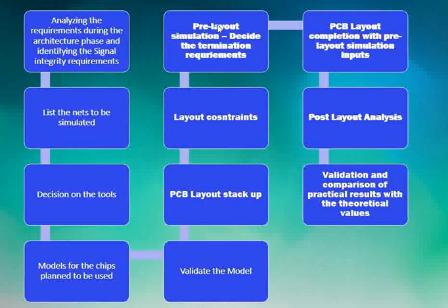And then one more important aspect while he gets these inputs is that a signal integrity engineer cannot directly use the model that is being provided by the manufacturers. He has to validate the model. That means he has to look into the model, see what are all the basic deviations that are present in the model, and see if the model requires some modifications from his end.